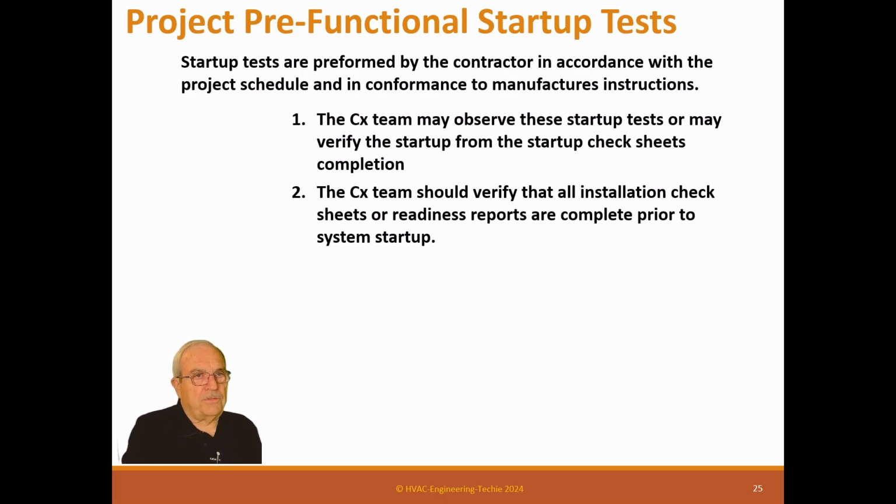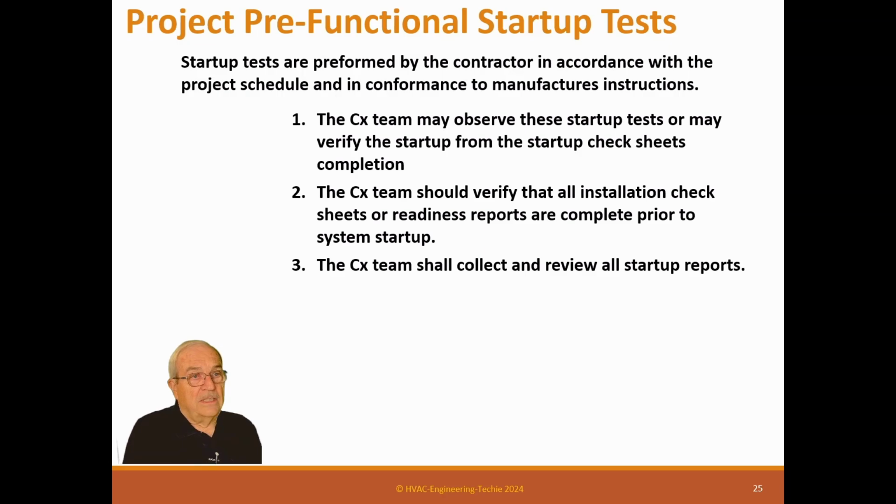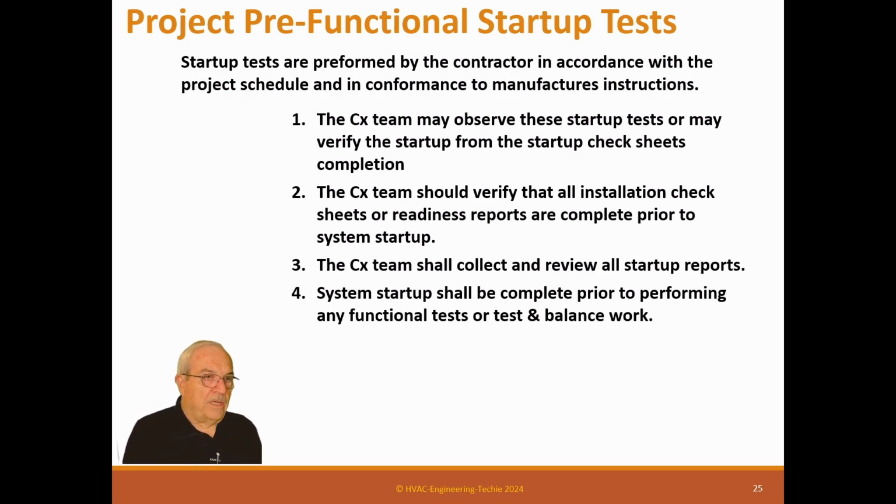The CX team should verify that all installation check sheets or readiness reports are complete prior to the system startup. So they should have already finished their pre-startup check sheets and should know what's going on with those. And if they don't have them done yet, they shouldn't be starting up a piece of equipment; they're not ready. The CX team shall collect and review all startup reports. Now, sometimes these startup reports are on cloud-based systems, which is easy. They should be able to give you your code to go look at it so you'll know when it's done or not.